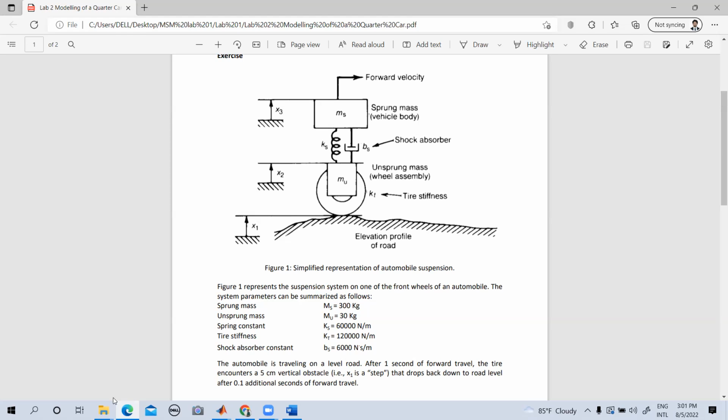The application would be different, and the overall system would be different, but the response and how it actually works would be quite similar in nature, right? So you can observe how these certain characteristics are parallel with each other. As an example, if you take a fluid accumulator, it's the same response as a capacitor, right? When you model the system, whether it's a fluid system or an electrical system, the capacitor you model similarly.